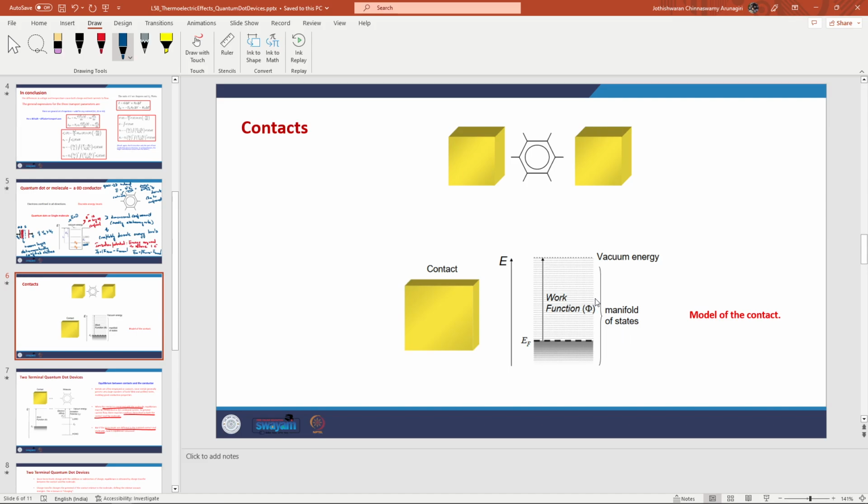So this is work function, phi, for bulk semiconductor, and ionization potential is for the completely confined channel. So the role of the work function is now replaced by the ionization potential.